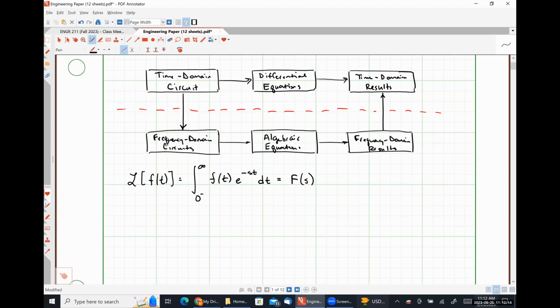Why does that matter? So we include the initial conditions on voltage drops across capacitors and currents flowing through inductors. Because if we start the limit of our integration at t equal to 0 plus, that's only applicable if our energy storage elements are starting from 0 energy storage. And that's not always the case. So this is what our definition of the Laplace transform is going to be.